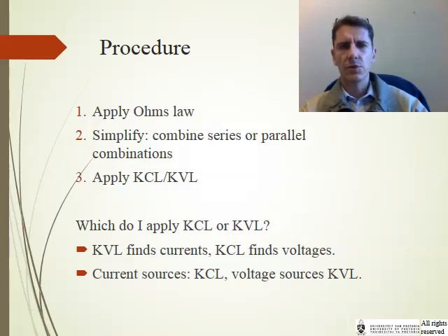We always first try and just use Ohm's law. That's the easiest method. If that doesn't directly give us the answer, then we need to simplify the circuit a little bit and maybe combine a few series or parallel resistors, and do that process until we have reduced the circuit to a solvable circuit.